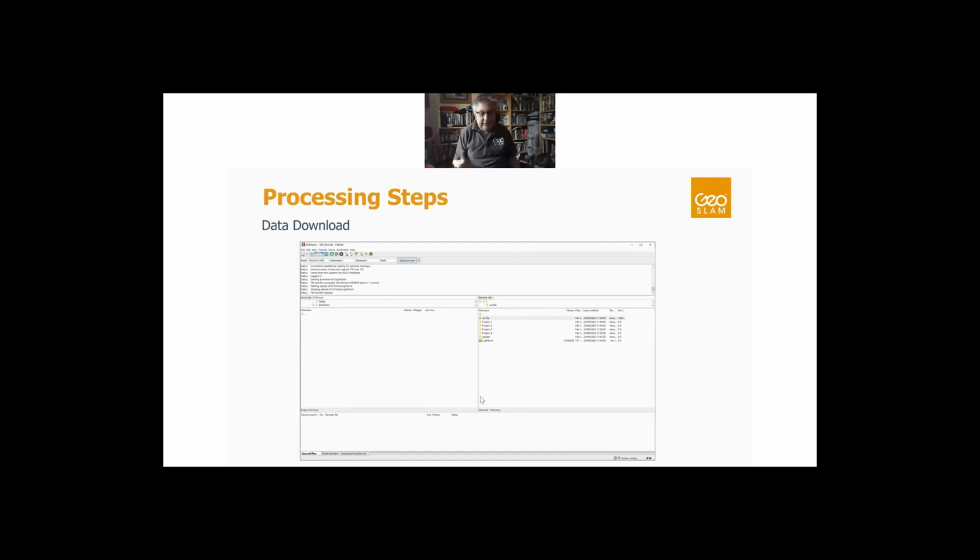At the moment, clearly, we need to store the cal file somewhere because that's quite important. So generally, I create a cal file folder on the camera, and that way I know where it is. I'm not going to lose it anywhere, and every time I take a capture, I can take a copy of the cal file and put it into the image folder, because that's implicit in how the stitching workflow runs in Connect. So potentially, if the stitching workflow fails for some reason, our first check is, has it found the camera cal file?